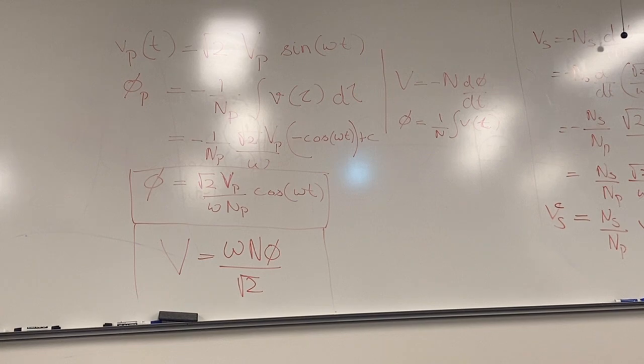So the easy way to think about turns ratio is always think in terms of voltage. You need to know in terms of current, but if you remember in terms of voltage, you are golden. Primary voltage divided by the secondary voltage is always number of windings in the primary divided by number of windings in the secondary, and that's a turns ratio. And it's so dead cheap to transform a high voltage to a low voltage on the secondary just by manipulating the turns ratio.